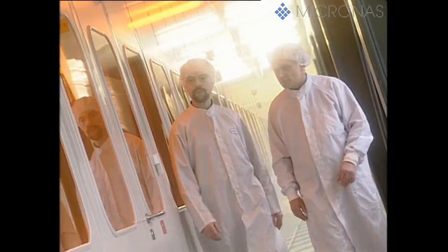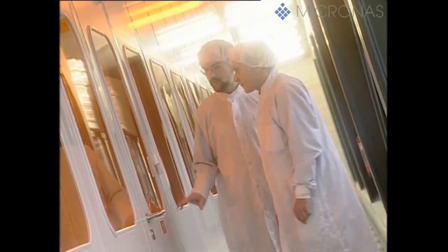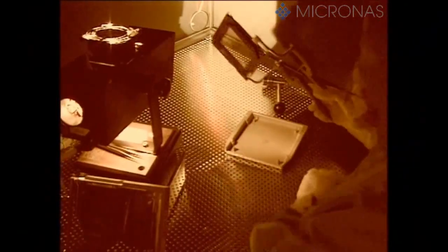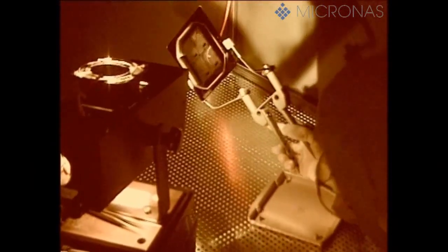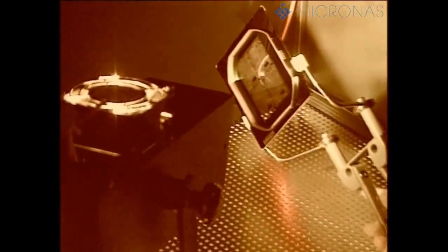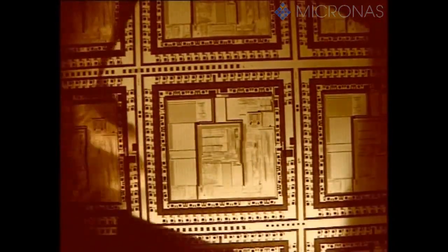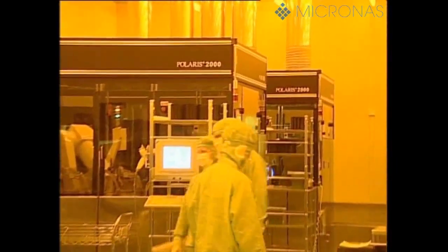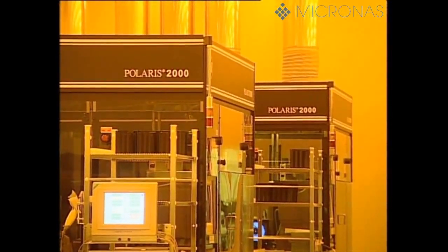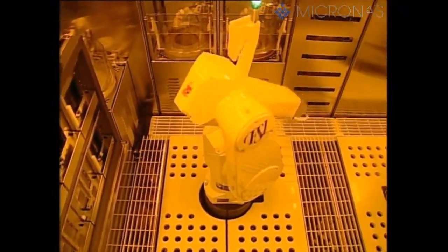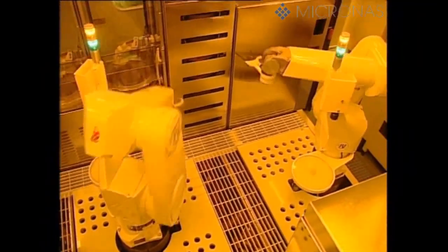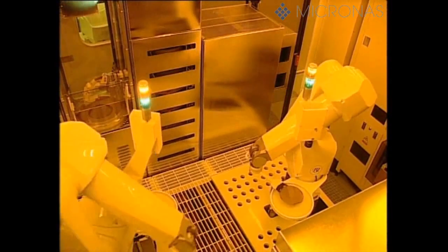The specific product being made, in other words a particular integrated circuit, is defined and structured via photomasks. Up to 20 individual photomasks are required to create functioning circuits from the bare silicon wafers. The photolithographic process is repeated for each individual photomask after the previous layer has undergone further physical and chemical processes, such as diffusion, ion implantation, coating and etching. In this way, the desired structures are generated on the wafer on a layer-by-layer basis.